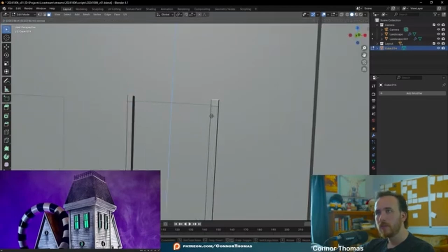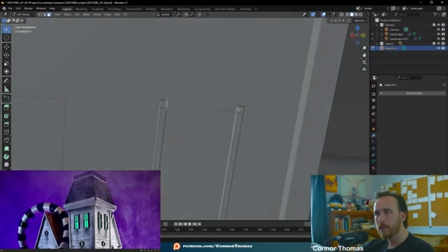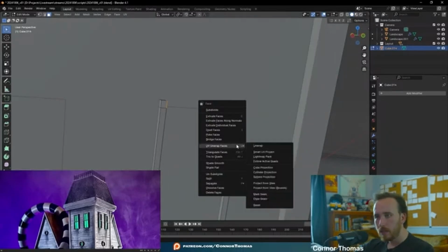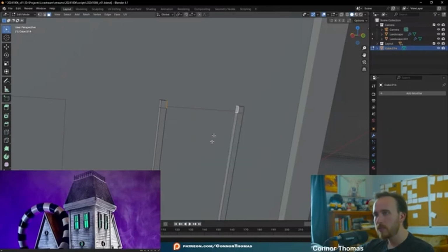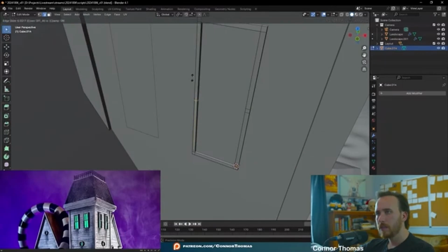Just extrude that upwards now, and right about there. Just grab these two faces there, and then we'll just go ahead and we will use, where's that at? Bridge. There we go. And I think if you right click this and add that to quick selection like he was saying, when you press Q, it just pops up on your menu here. Only thing I might do is add in something like this and do the same on the other side.